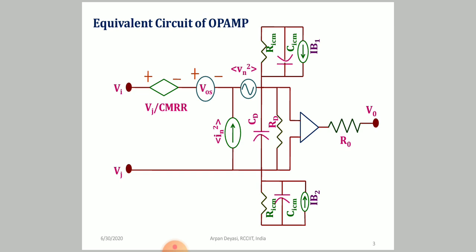And after that, you have the drain resistance. So there will be Rd, and Rd will be parallel with the Norton source and in series with the voltage sources. And you may have some sort of differential capacitance. You can't say that you don't have a capacitance and it's purely resistive. Never. There is a chance of a capacitance factor, so you have to account for the differential capacitances when you are dealing with the AC signal. Naturally, there will be CD, in parallel with RD. That means it forms a sort of tank circuit that controls the frequency.